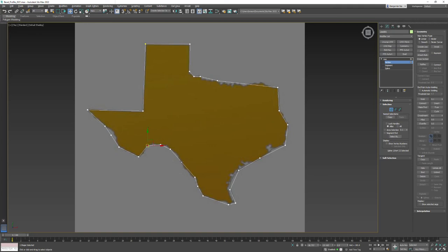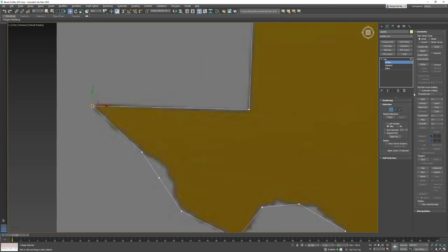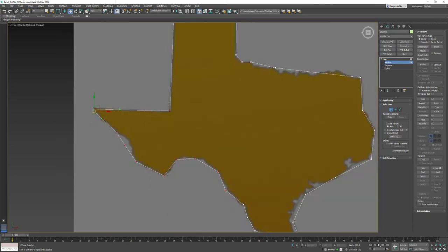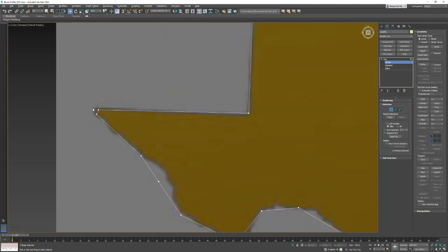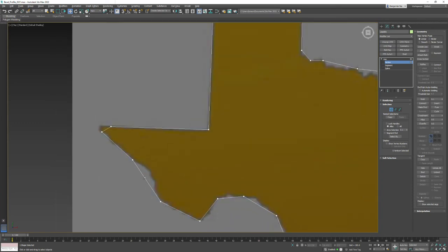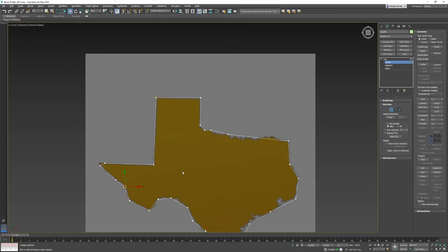Another one in there. And then I don't like having it come out to a point as extreme as this one here, so I might actually come in and just chamfer that a little bit. There we go. And maybe I'll chamfer it. Let's make sure we're keeping all our points corners though. And really, I'm only keeping them corners for the purposes of the projects that I'm specifically doing. There's no problem with making splines with rounded corners. It's actually what makes the tools very, very cool and fun to work with.